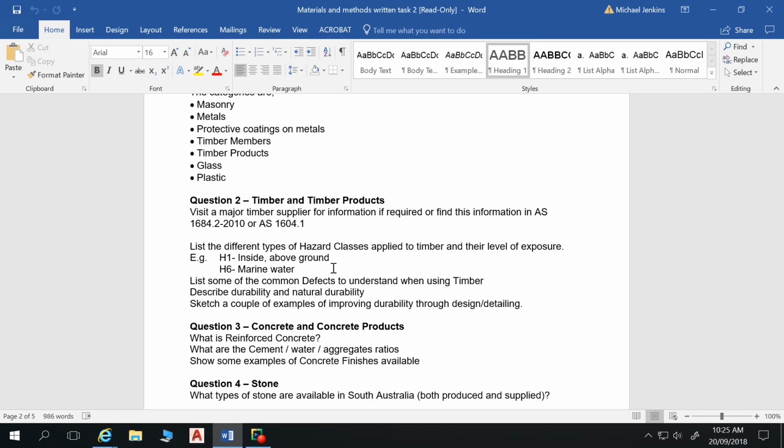Other things, this is something you'll see a lot on pergolas. If we've got our rafters heading like that, for example, this portion of our timber is a fairly vulnerable bit of timber, and where we have all our end grain going like this, that's a position for water droplets to sit and start soaking into that timber. You've probably seen that on pergolas, things left outside. That's where they start rotting.